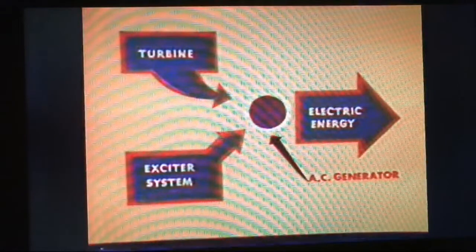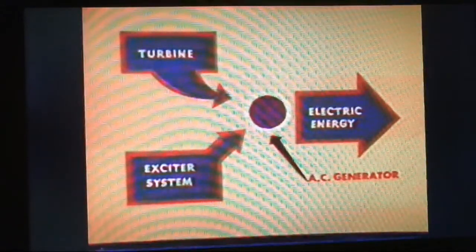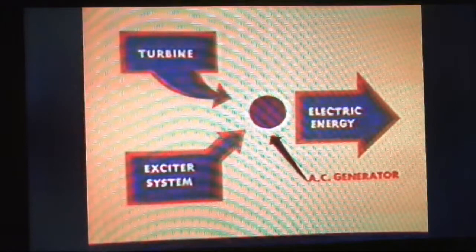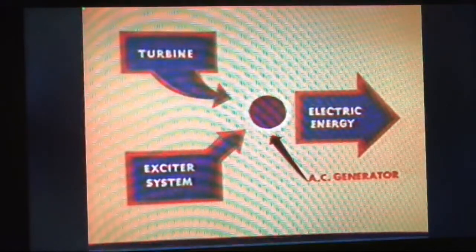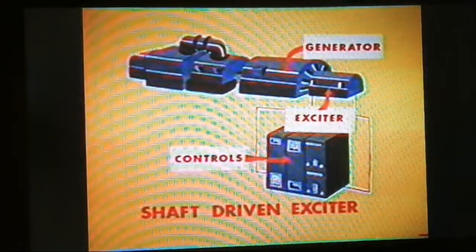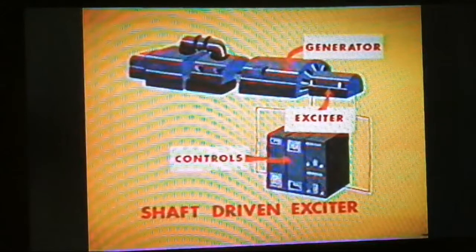The mechanical energy which causes rotation, together with carefully controlled flux fields, are necessary for the AC unit to function effectively as the loads change. Loss of the DC field, even for a very short time, can cause serious voltage disturbance to the generator. The exciter must have a reliable source of power. Often the exciter is driven from the main generator drive shaft, called a shaft-driven exciter.